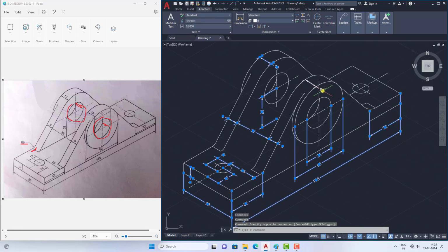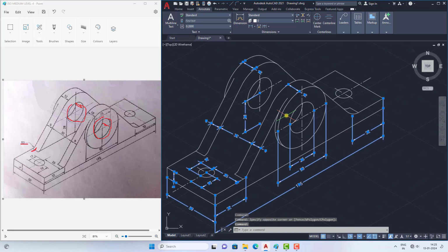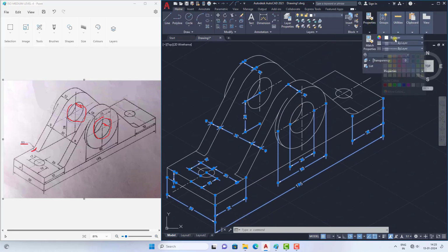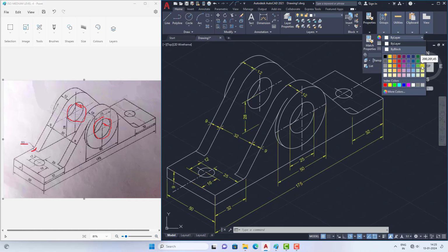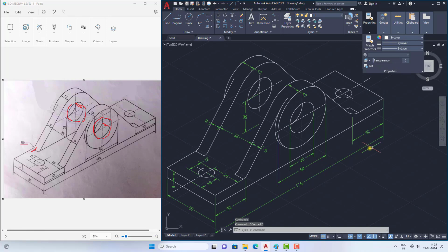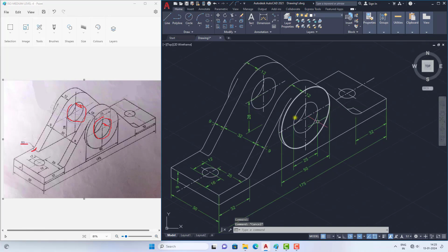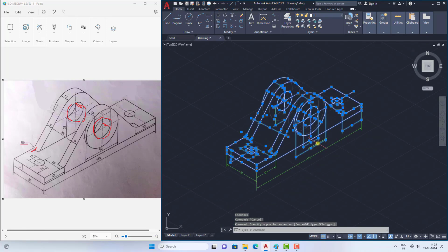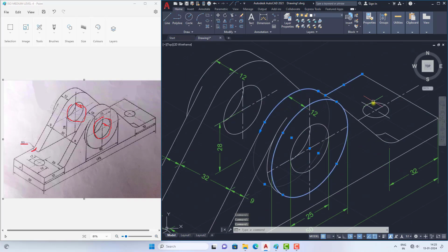So see, these are all my dimensions and I am going into the home tab and selecting properties by layer, and giving the dimensions some colors. You need to give light colors only. Now I need to select the diagram also. So once check, I am selecting this diagram.